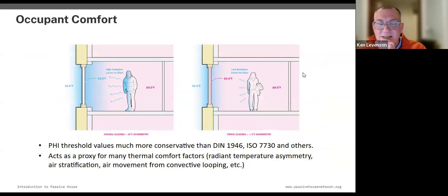One of the things that drives that with Passive House and differentiates it from normal construction is when you have these temperature differentials, so it's cold outside, the temperature of the glass can drop significantly, and you feel it pulling the heat off of your body, and you need to overcome that. It causes convective currents, and you need to overcome it by having perimeter air conditioning, radiation, heating and cooling.